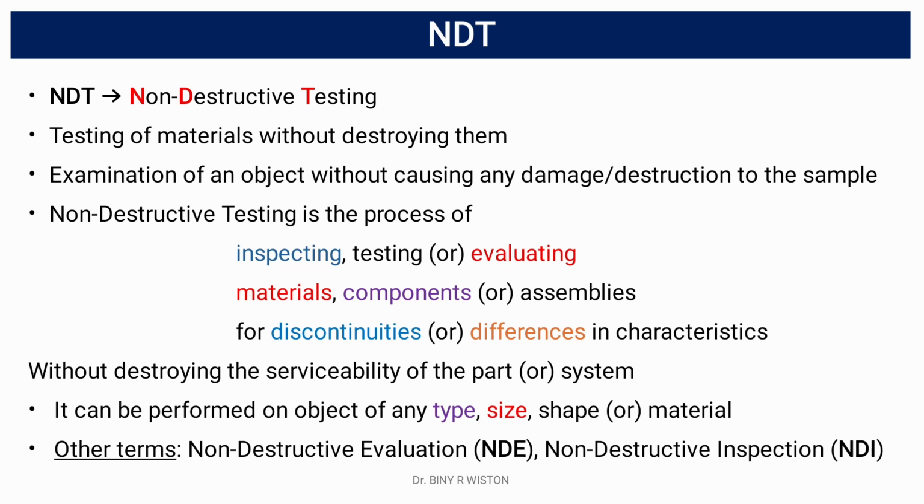The other terms which are used to denote NDT are non-destructive evaluation and non-destructive inspection, which can be shortened as NDE and NDI. The major task of NDT is to detect and identify the range of defects which may be produced due to production flaws or fatigue cracks.